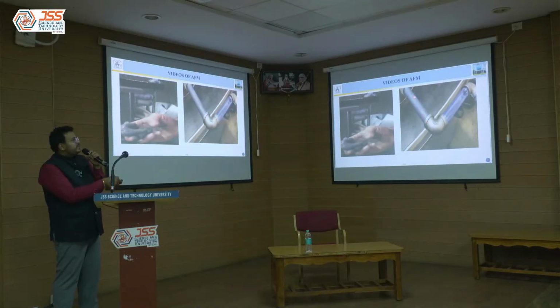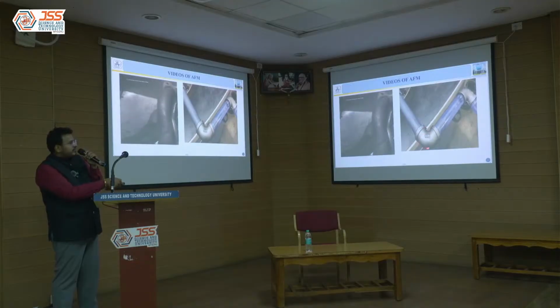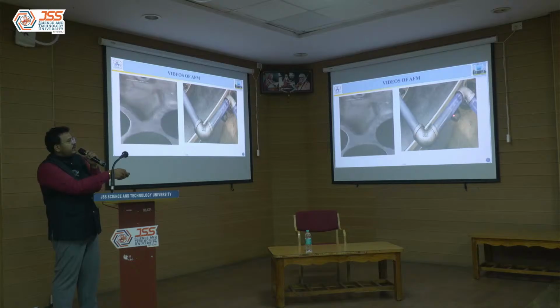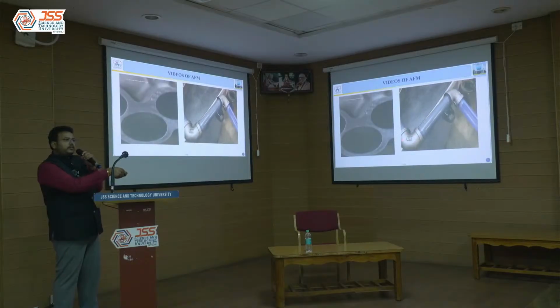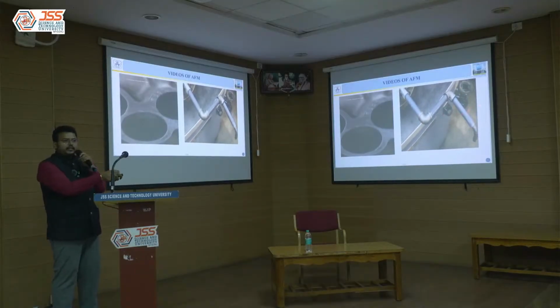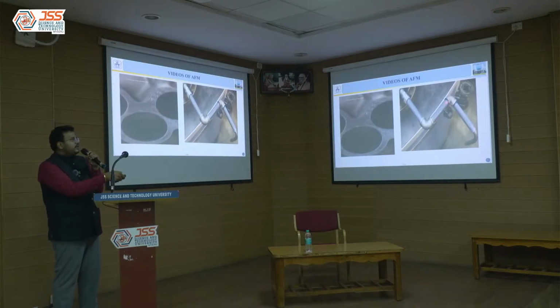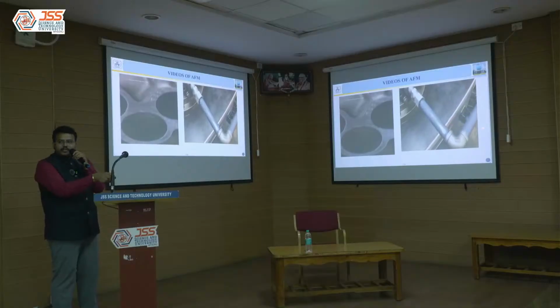So we are pumping the semi-solid media to and fro, passing through the target surface. See, this is the workpiece here, and this is the tool. While pumping, it is doing its job, cleaning the internal surface, deburring it, radiusing it, and you can have a controlled finishing using sensors. We are using some acoustic sensors to predict the surface roughness without measuring.